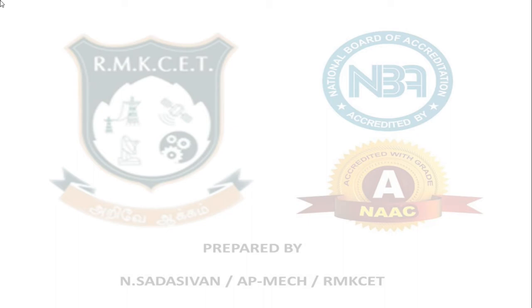You know, I have studied in the second unit, balancing of reciprocating masses. There will always be some unbalanced force left inside the system, swaying couple. A lot of forces are left behind, which is going to disturb your vehicle or the frame on which your engine is sitting. This is going to create some additional deflection. The dynamic magnifier is the ratio between the static deflection and the dynamic deflection.